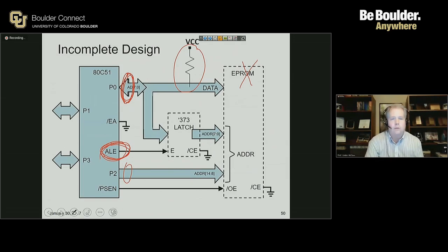When you first solder in the 27 picofarad values to C1 and C2, some of you may have a completely operational oscillator at that point. It may work perfectly fine. Some of you may find that it's oscillating at a higher frequency.